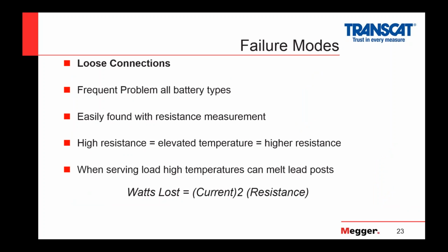And the last thing we're going to cover is loose connections. This is something that gets overlooked so much when testing batteries. People look at testing the batteries, but don't think about the intercell connections, the straps on them. This is critical because now think about the string, which you have. You have all these cells connected by these straps. And if you think about it in your head, you can picture these as little impedances, little resistors.